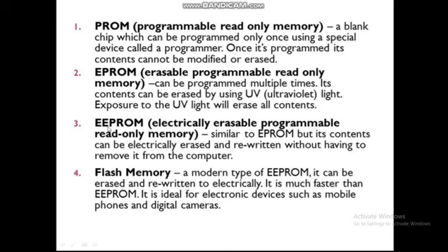One of the main disadvantages is that for erasing, writing and reading and storing information, we need different voltages. That means it uses a complex memory cell structure, and it has low density, but also high cost and lower reliability. But it is very useful because we can erase according to our need.